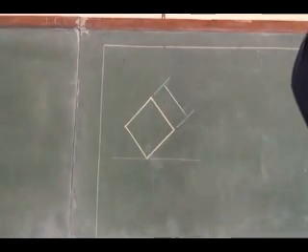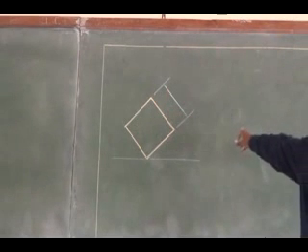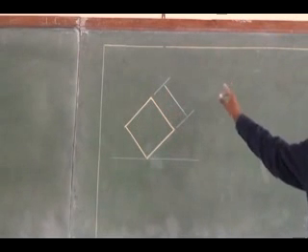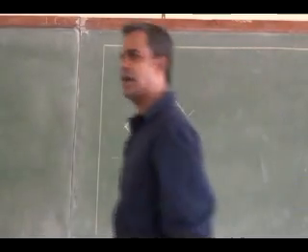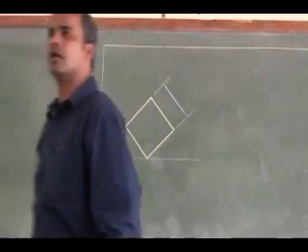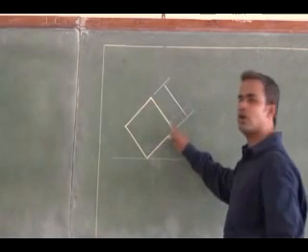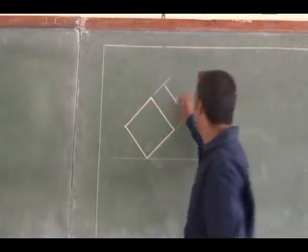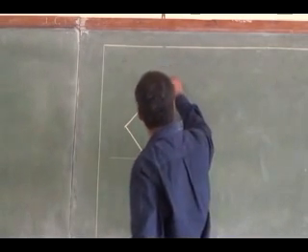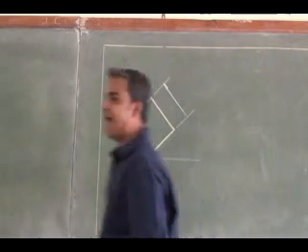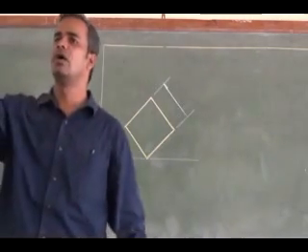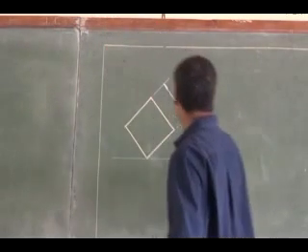I mean, you no need to ask. If it is in white color, that is 2H. Right. Yellow color, that is an H pencil. Right. So this gap you have to maintain, 10 mm gap. So then you dimension, put the arrow head as small as possible, maintaining 1:3 ratio.